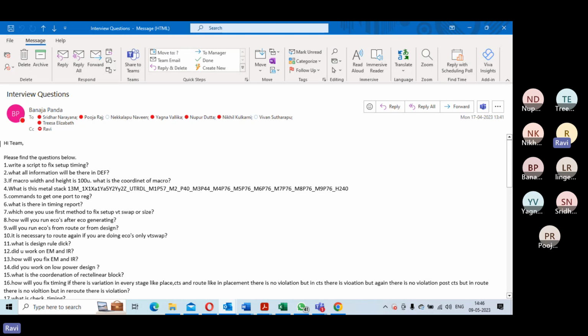Okay, and now if you are actually having delays which are like 30 picosecond, 40 picosecond, and so once you have actually addressed all this 0 to 1, right? Any drivers like 0 drive cell or 1x drive cell or 2x drive cell, which is actually giving you large delay, you should try to upsize them. Now, if they are drive cells like 3x, 4x, and still you have this violation, you should try to swap them. Then you look at VT swapping.